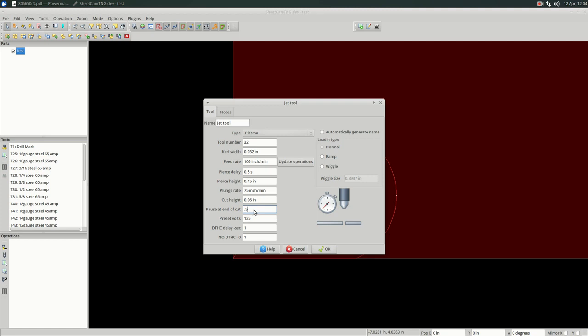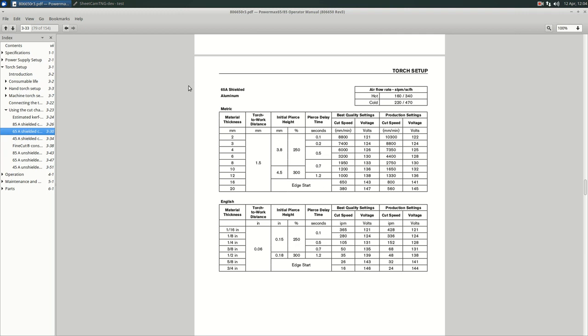happen so quick and there is a time delay from when the computer shuts off a plasma cutter till the arc is fully extinguished. We have found that 1/2 second to 1 second seems to be sufficient. The voltage, I cannot remember, it was 131.